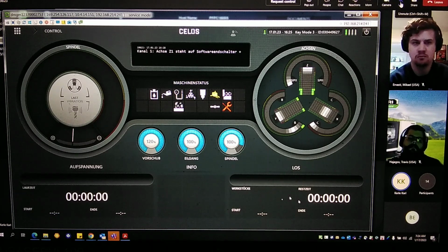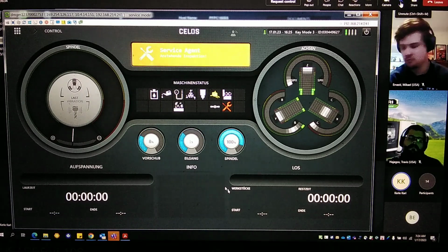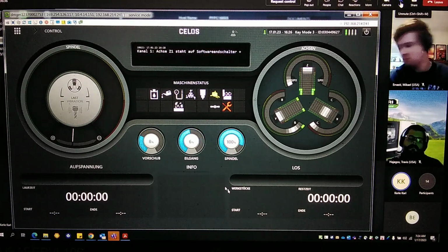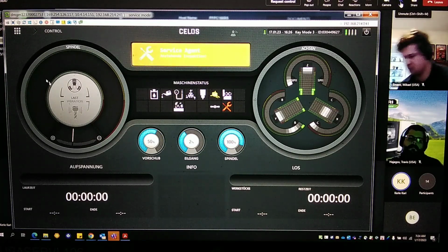This you can see here on the status screen, also the position of feed rate and rapid speed override. Also here you see when I turn the potentiometer, the value here is changing. That's the blue circle, bigger or smaller. In the center you see a percentage value indicated, as well for the spindle.